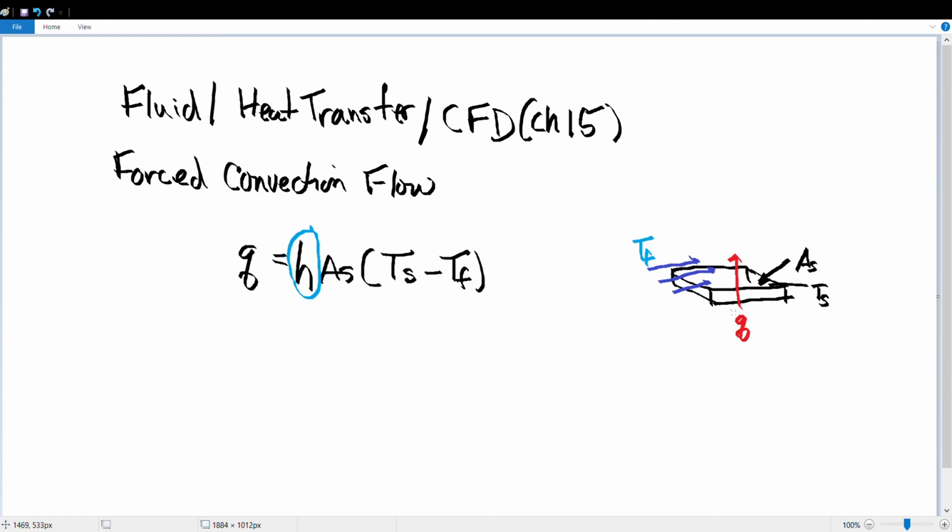If I gave you the amount of heat that's being dissipated here, then you would be able to calculate the temperature of the surface, for example, given a heat transfer coefficient. And you'll notice when you go into industry, this is the big question here, right? What's your assumption there? A lot of people will go into handbooks and just pull different heat transfer coefficients.